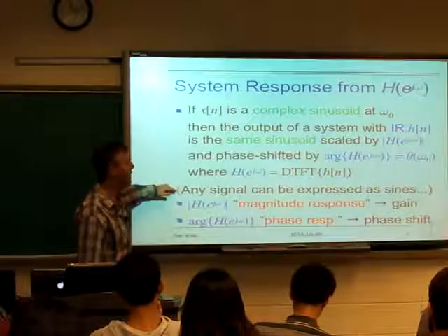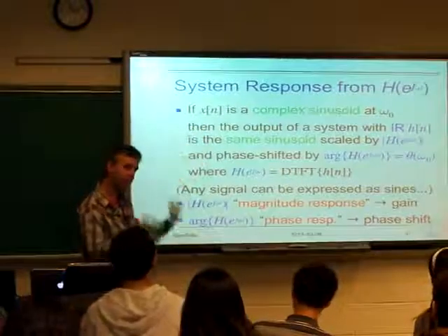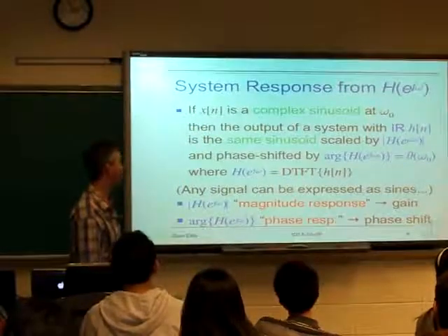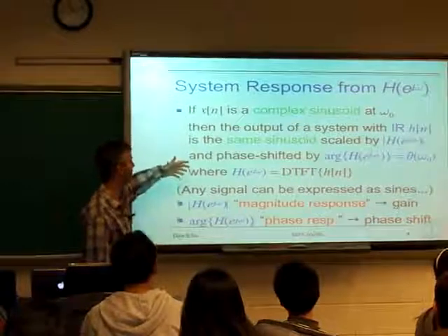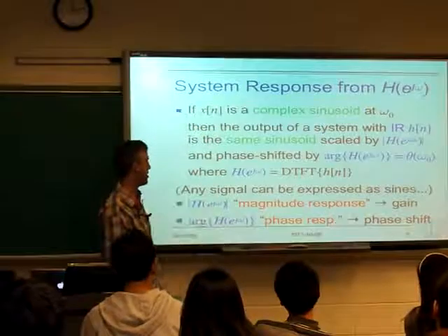And because we can take any signal and break it down into individual sinusoids, that's what Fourier analysis does, this generalizes to any signal, not just individual complex sinusoids.